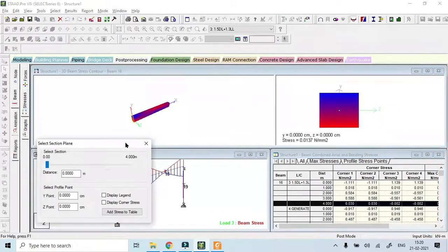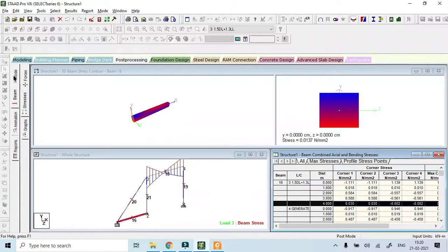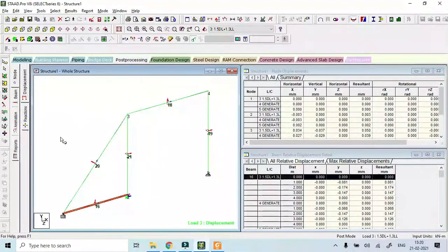Now one thing which I would like to stress is that if I go to node here, this corresponding thing is actually a visual display. This is actually showing the displacement. You can see here at the top Fx, Fy, Fz, Mx, My, Mz. Fx is axial force, Fy shear y force, Fz shear z force, Mx torsion, My bending moment, Mz this one, and then you can see deflection. Now deflection is on, but you cannot see the deflection properly because it is very small.